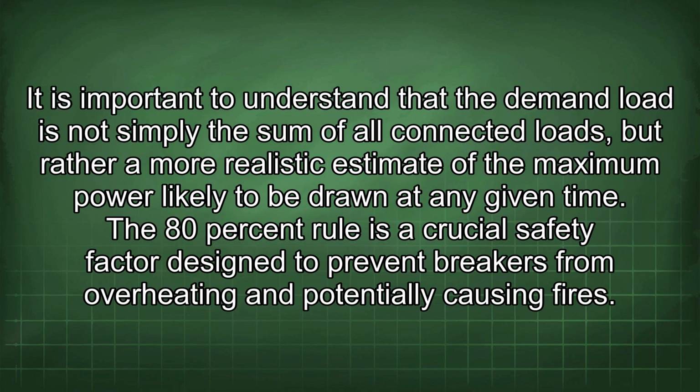It is important to understand that the demand load is not simply the sum of all connected loads, but rather a more realistic estimate of the maximum power likely to be drawn at any given time. The 80% rule is a crucial safety factor designed to prevent breakers from overheating and potentially causing fires.